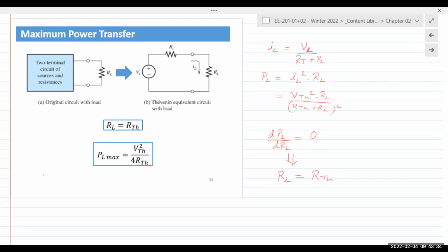Okay, so in cold weather, that voltage value does not change. That still remains the same. But the chemical reactions occur slowly, so the Thevenin resistance of that battery is much higher. So if the Thevenin resistance is higher, what happens to IL? It's much lower. And so to turn on the ignition coil, to turn on the engine, it requires a certain amount of current, and that current would be lower. And that's why you might have trouble if the battery is kind of old.